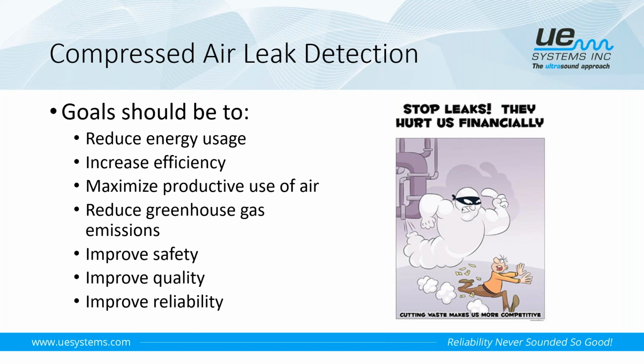In some cases, there may be some safety concerns related to air leaks, especially if you have some of the higher pressure systems where you're doing specialty types of applications. We really haven't talked about specialty gases, but we're basically talking about any kind of pressurized gas, whether that be compressed air, whether that be hydrogen, helium, oxygen, argon, any kind of pressurized gas, we can use ultrasound to check for leaks. In some cases, there may be quality concerns. So product quality may be of concern if you have excessive leaks on your system.